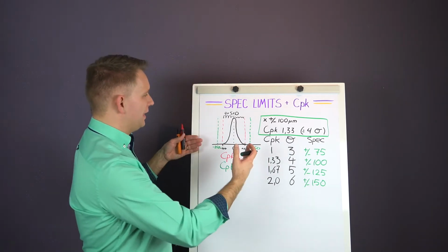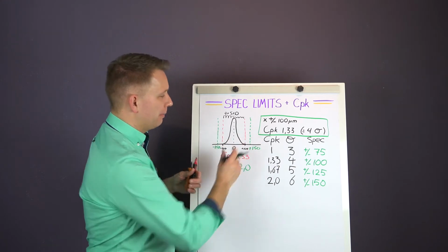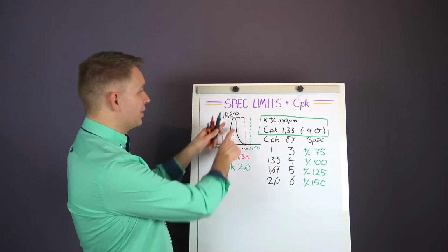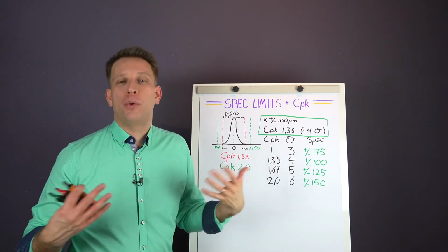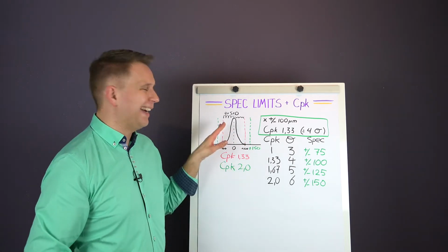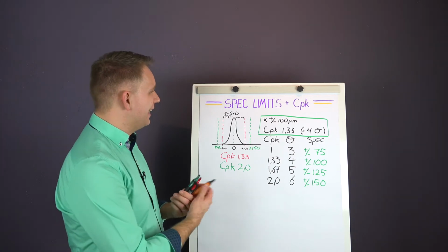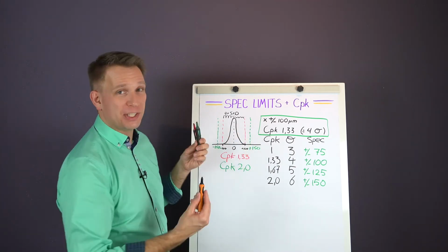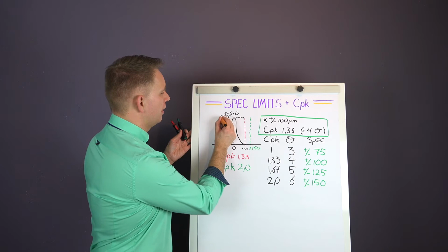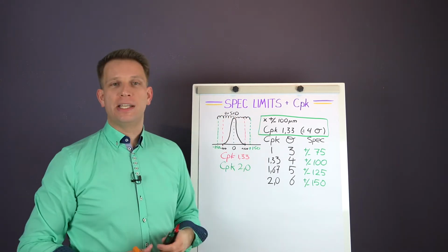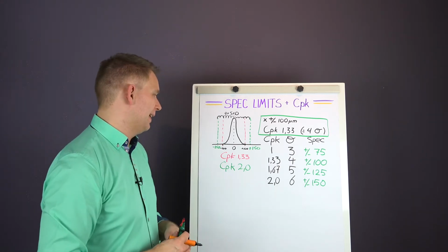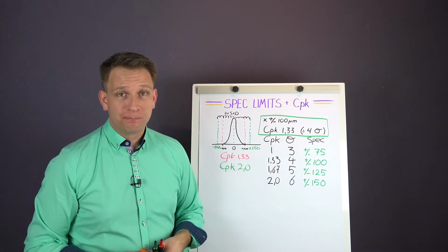So if you take minus 150 plus 150 as specification limits, not changing the process at all. You see, right, the black line, our product coming out of our process, I haven't touched it. What I simply did is broaden the specification tolerance so that I can put 2 more standard deviations in on either side. And then we get to Cpk of 2.